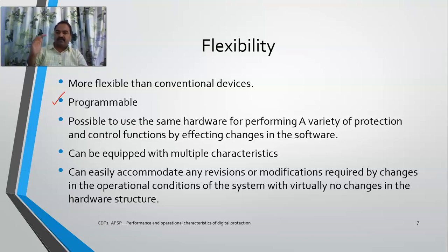You can vary the level. Very simple. Just by writing a program, you can vary the pickup value. You can change the threshold values, or you can change the conversion, or you can go with some other frequency measurement technique. It's all about a good software programmer who can write an efficient program so that the application can be changed completely. So this is just like the relay being more flexible for you.